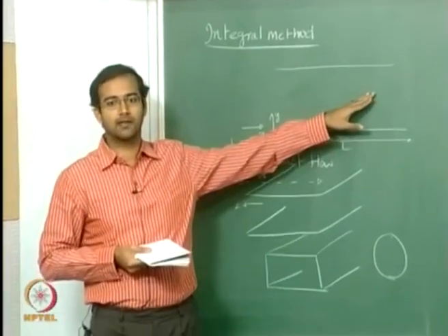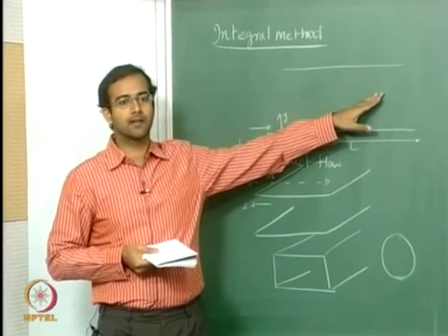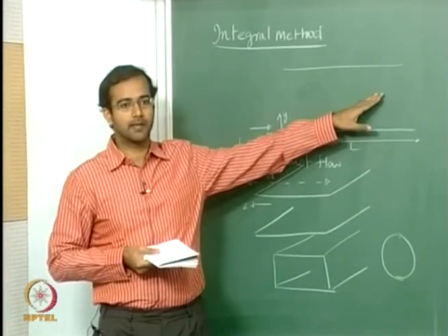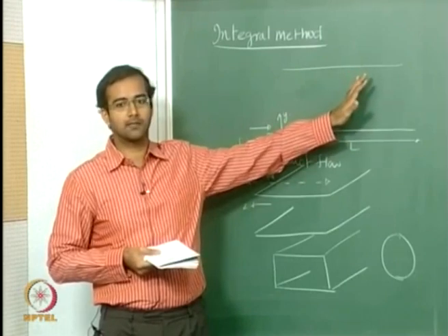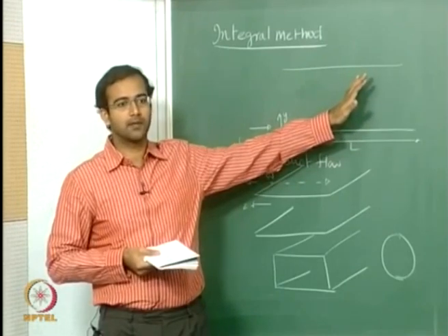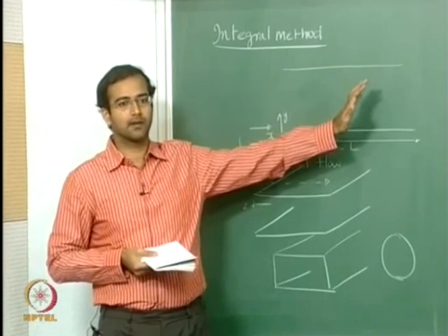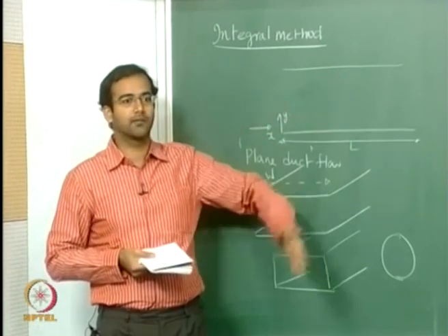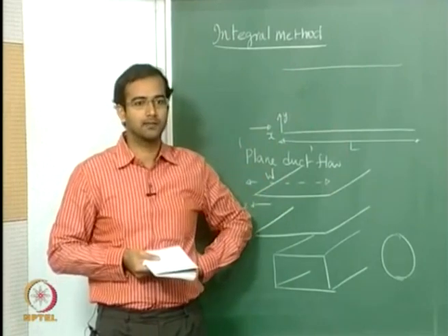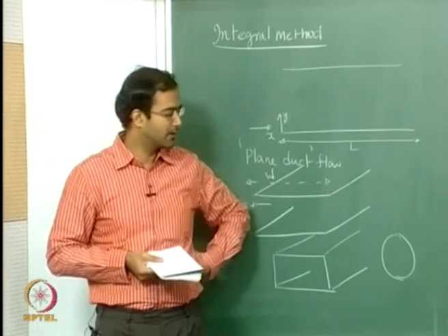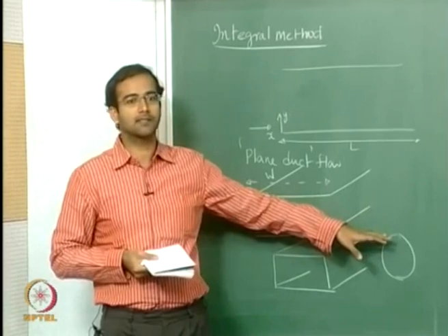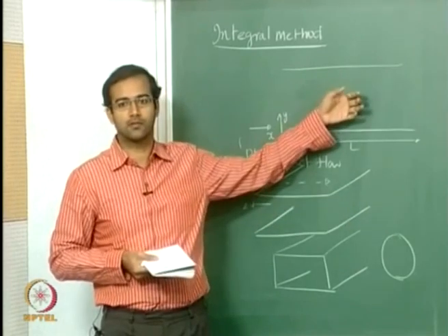We neglected the radial and the tangential components, and the radial component was included in the conduction part, of course, but when we looked at the energy balance, we neglected the dependence on the theta direction, the azimuthal direction. So therefore, strictly speaking, what we considered so far were 2D axisymmetric.